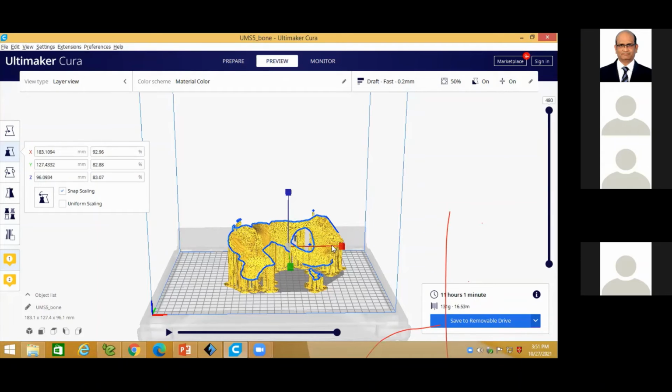So you have to play with something. You have to change the different orientation, and you have to optimize the material. You have to optimize the time to utilize your printer effectively. Like that, you have to change the different orientation and different fill percentage and infill percentage. You can choose the different infill patterns, and you have to choose the various support structures also here. Okay, all these options you can see here.